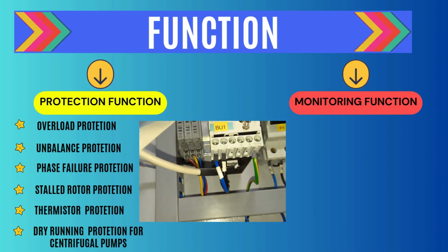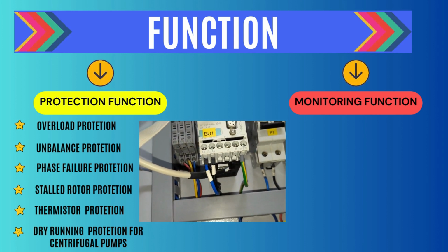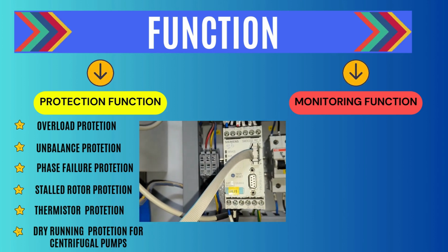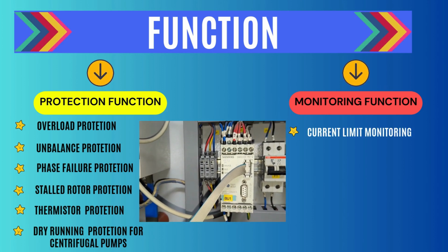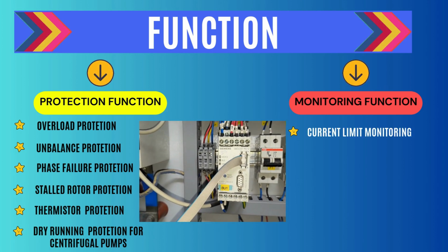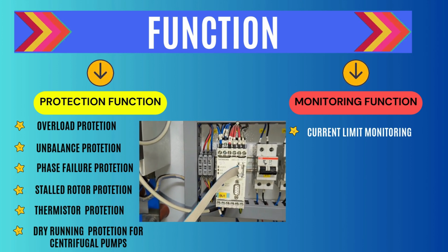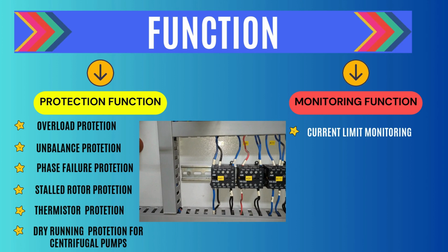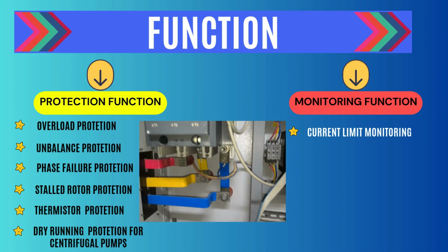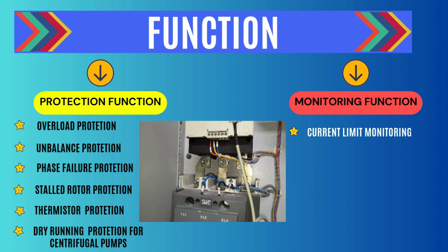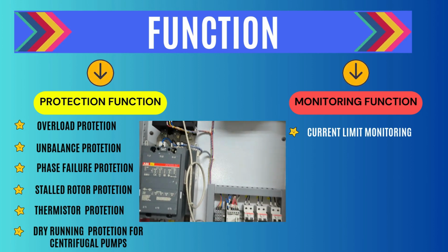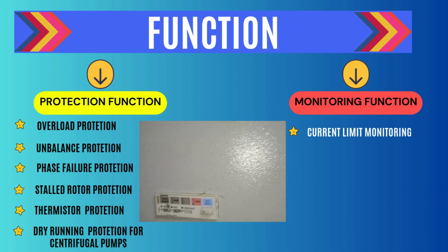Current limit monitoring is used for monitoring, enabling incidents and anomalies in the system to be detected in good time. If a current limit is exceeded but still below the overload limit, it can, for example, indicate a dirty filter on a pump or increased friction in a motor bearing. If the current limit is undershot, it can be the first sign of a worn out drive motor belt.